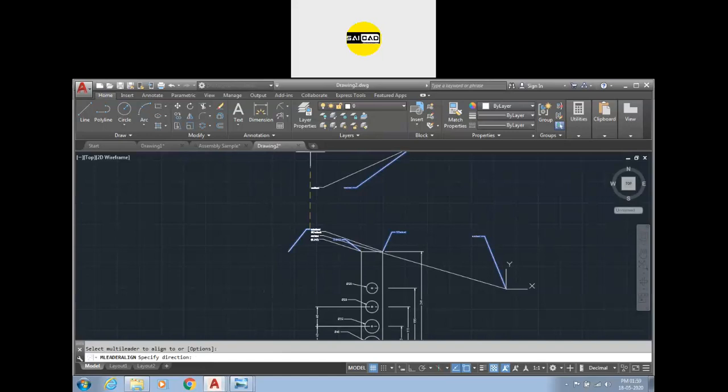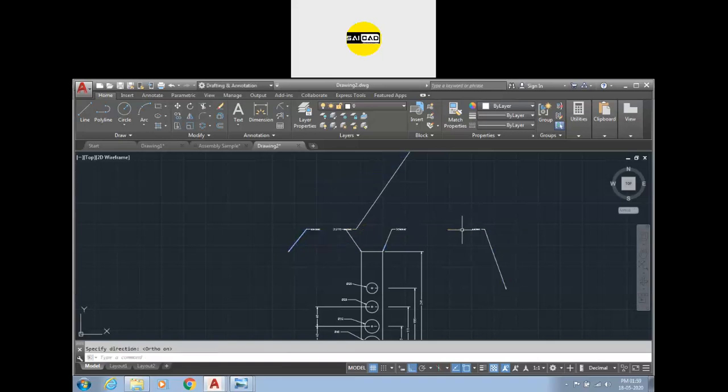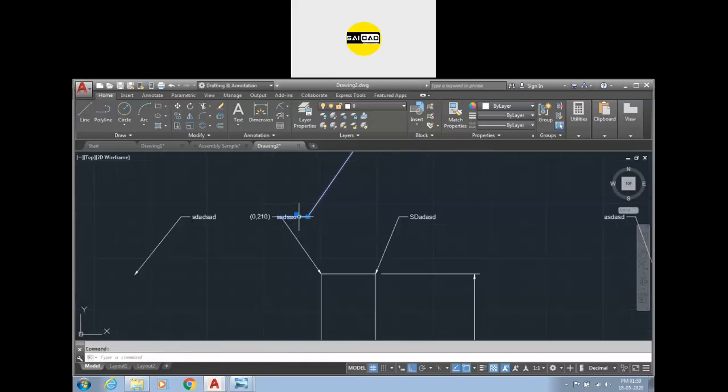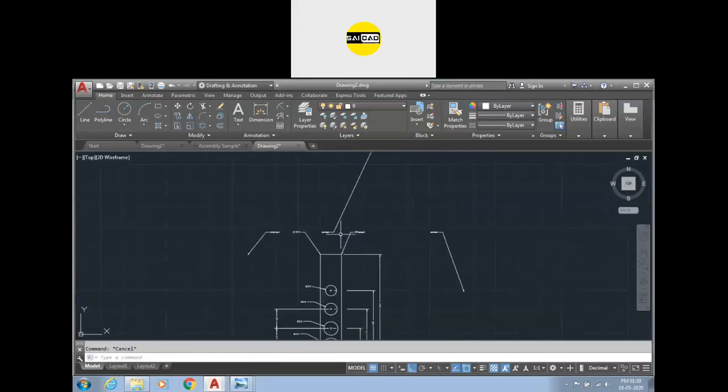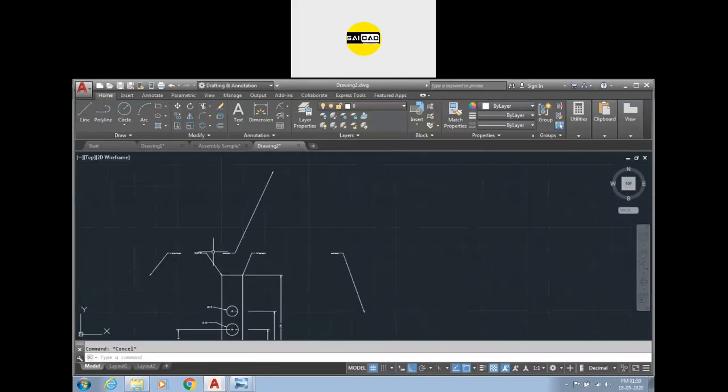I want to align with this leader, so it can be horizontal, it can be vertical, whichever you need. I'm going to just create a horizontal. So press OK, and the leaders are aligned like that. If you want vertical, you can just select the direction to vertical. So these are the basic types of leader options you can use from the leader command.